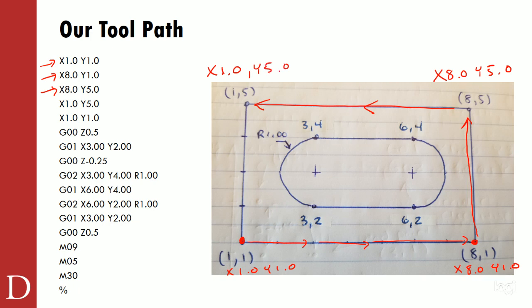And then I do want to cut this path too. This is part of my tool path, so I don't want to stop at this point. I want to make sure I continue cutting. So I'm going to cut down back to X 1.0 and Y 1.0. So you'll see that again. So there was my 1.5 and there was my 1.1.